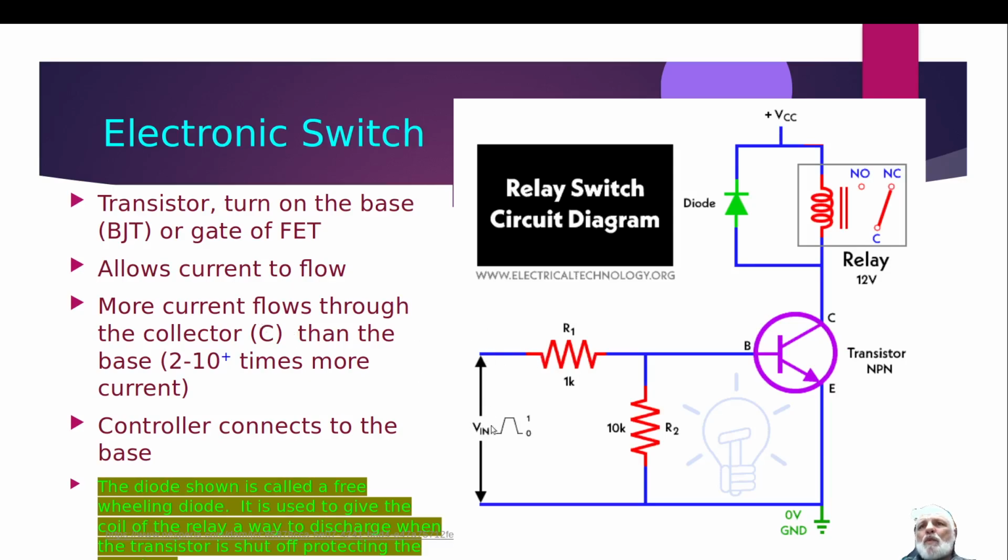by putting a 1 or a high out, so we have like 3.3 volts here. Now this transistor, between B and E, where B stands for base and E is the emitter, wants 0.7 volts. Our Beaglebone is going to output 3.3 volts, and this transistor only wants about 0.7 volts.